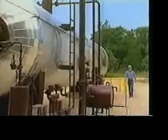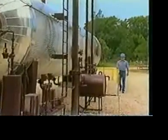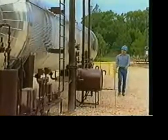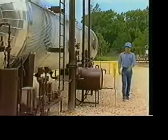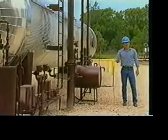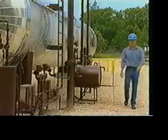A horizontal heater treater is a pressure vessel which combines all the equipment necessary to treat an emulsion. Sometimes it's referred to as a flow treater or an emulsion treater. Like other treatment equipment, heater treaters are designed to break an emulsion and allow water to settle out, so only clean oil and gas is transferred to pipelines.